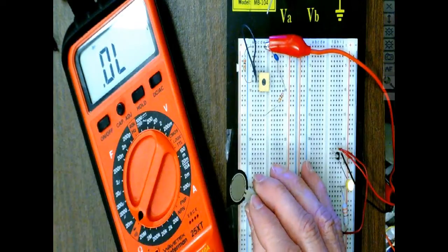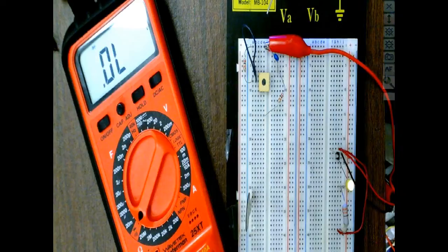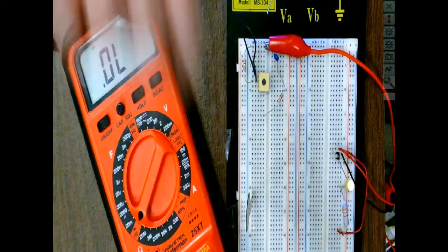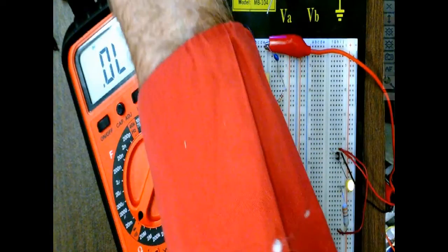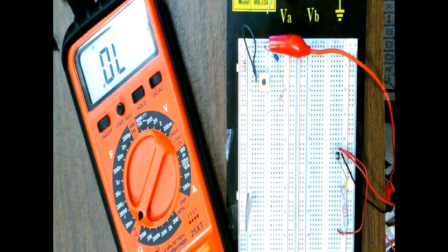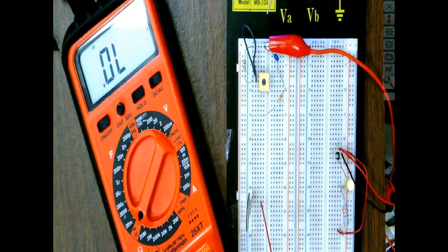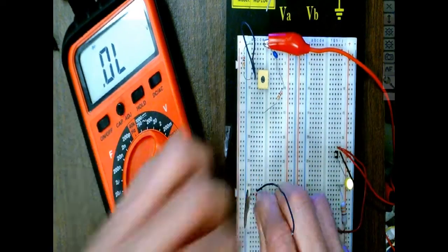Okay, and what I'm going to do is put my ohm meter across it. And let me find my other connection wire, and then hook up a couple wires to it. Now this is another thing that varies its resistance. So we do have to run this through a fixed resistor or a Wheatstone bridge for the change in resistance to actually mean something. Let me make sure I got it on the leads.